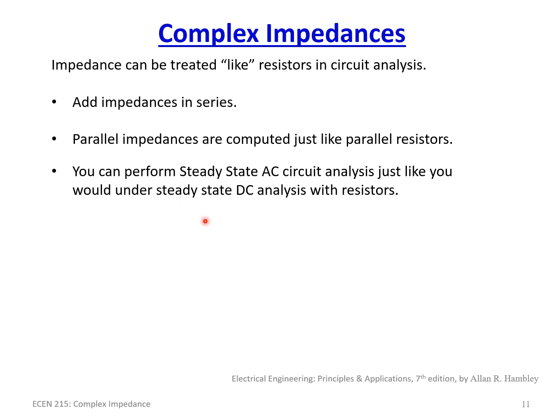You can't do that here. You have to go through and compute all the impedances, and now all the impedances become basically little boxes with an impedance value, and then you will go through and perform the nodal voltage and mesh current analysis, and we'll be going over that in a later lecture, just like you would previously, but now with complex numbers, these impedances.